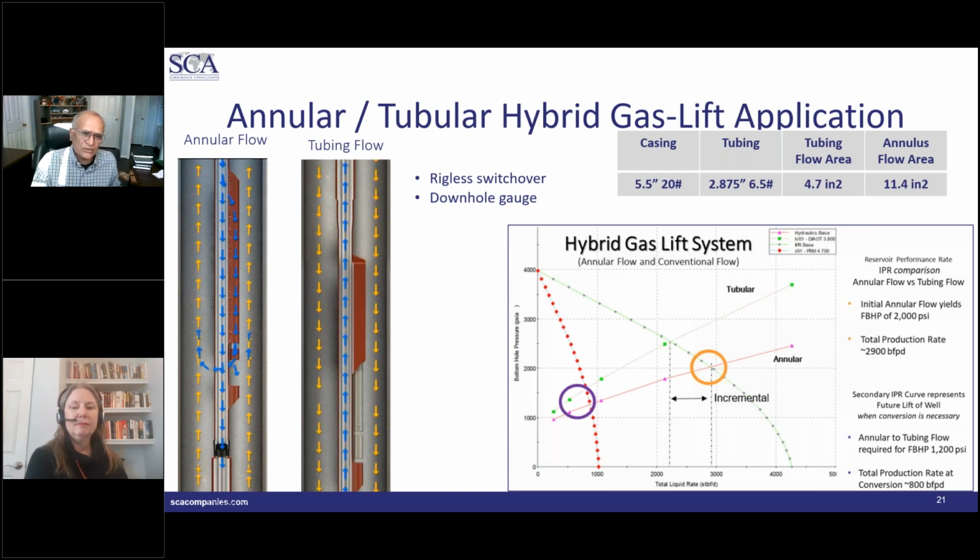So using those remotely operated valves, one of the promises is that you can activate and deactivate the valves at a particular depth depending upon your well's productivity. Plus, you have downhole data coming in from the associated pressure and temperature gauges, but it doesn't make them cheaper though. Okay?